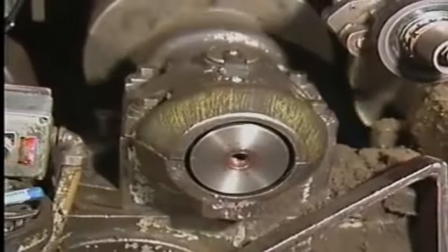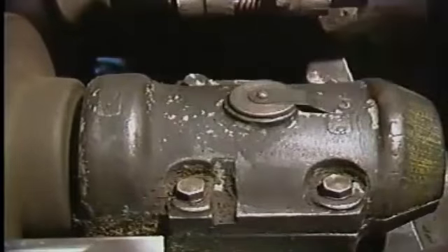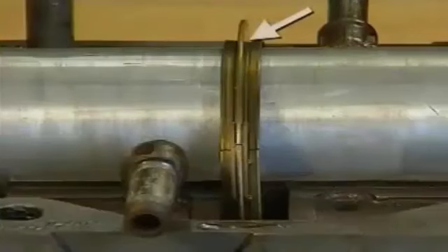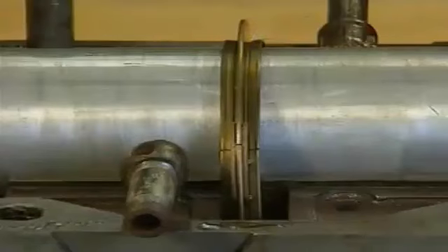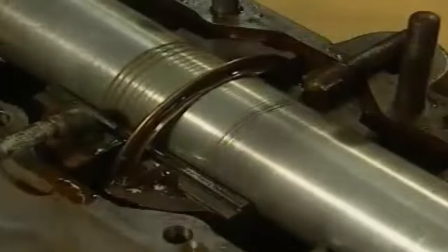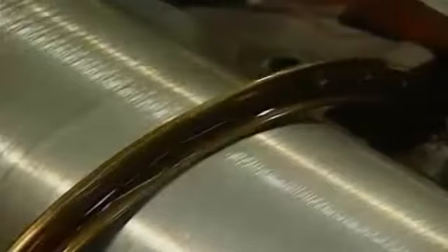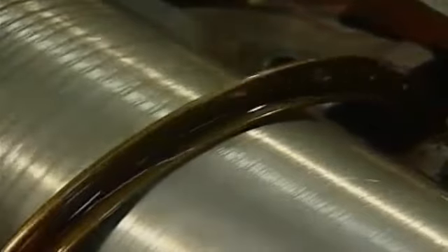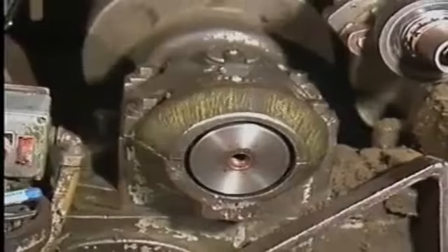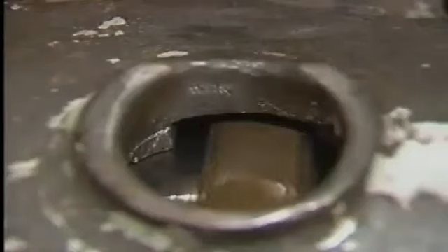Sliding surface bearings are usually lubricated with oil. One common oil lubrication system is an oil ring system. In this system, a ring rests directly on the shaft. The lower half of the ring is submerged in oil in a reservoir located in the lower half of the bearing housing. As the shaft rotates, the oil ring turns, carrying oil from the reservoir up to the top of the shaft. The oil spreads across the shaft, and any excess runs back down into the reservoir. In a piece of operating equipment, as the shaft continues to turn, a continuous film of lubricant forms between the bearing and the shaft.